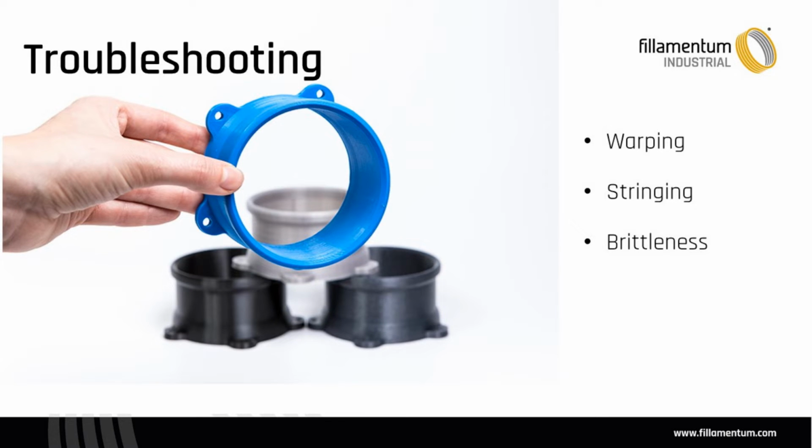It can be caused by several reasons, like too low temperature on the hotbed and also on the hot end, also too much cooling of the part. Warping could also be connected with humidity in the filament. If you have a wet filament, it increases the warping effect of the nylon, and the adhesion isn't as good as with dry filament.